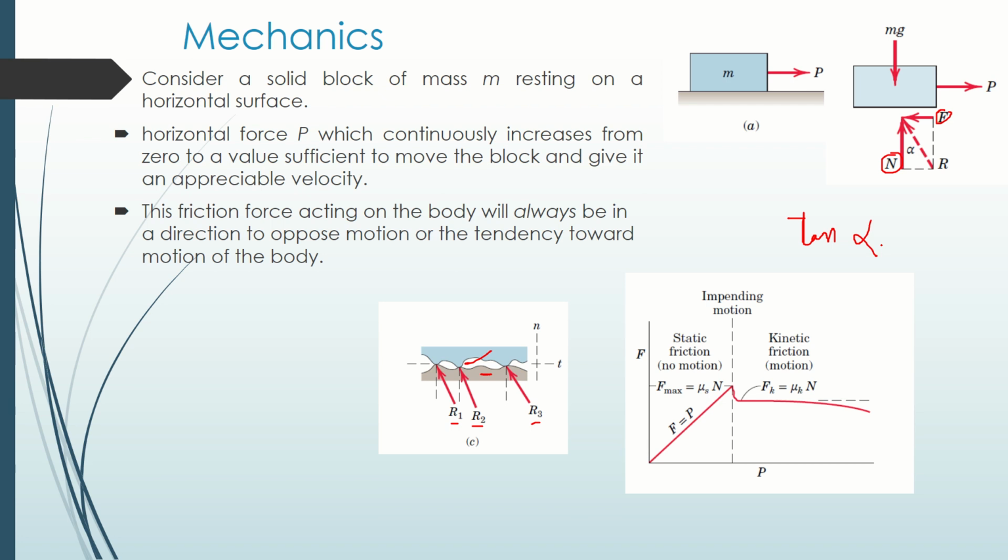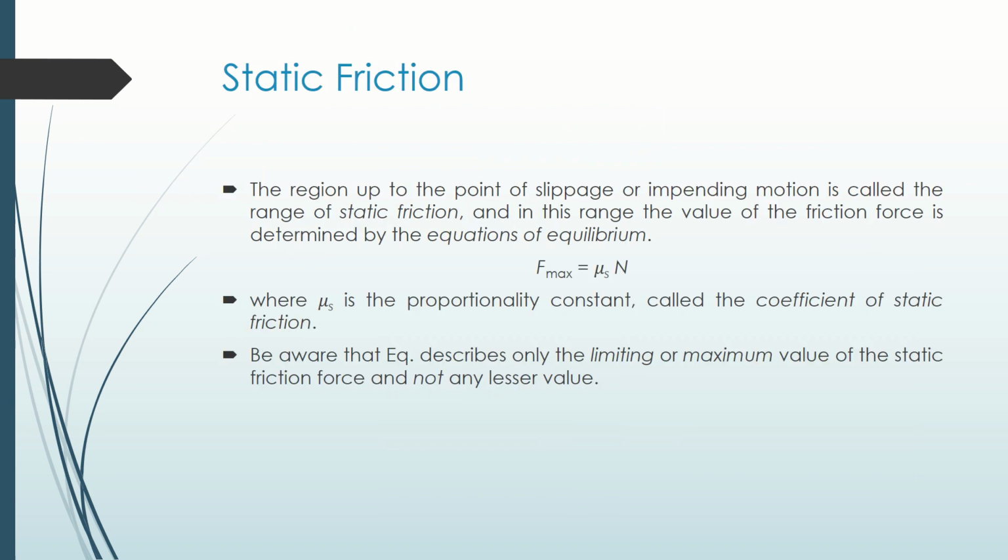Now you have to understand, the more speed you increase, the faster you move. The faster you move, the less normal force tends to act on it. As a result, your kinetic friction can even go lower. In order to reduce friction, you can introduce a thin film of lubricant. So it will reduce the overall static friction coefficient, but also will reduce the kinetic friction. So these things are the basic mechanics of the surface friction.